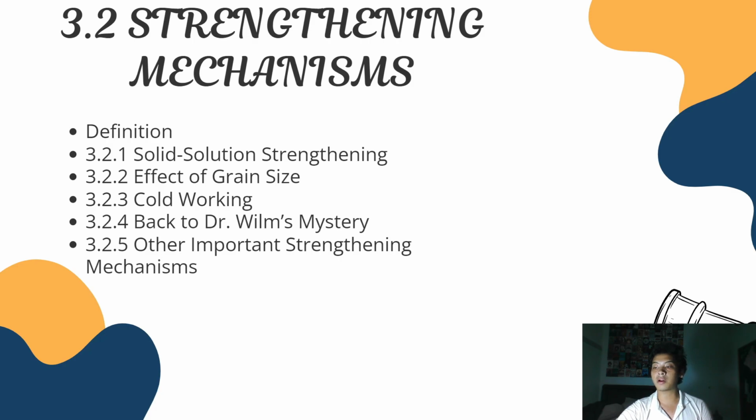In zone 2, maximum hardness is reached. The solute atoms move about and form small particles, attempting to form the precipitate phase. The precipitate remains coherent with the aluminum lattice. Strength increases significantly. In zone 3, the precipitates grow in size with continued aging and tend to become non-coherent. With the loss of coherency, reduced lattice stresses result in decreased hardness.